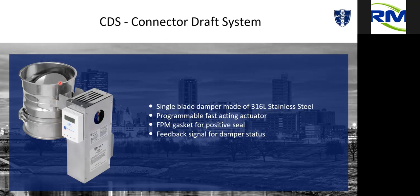Question came up, what sizes? These come from 4-inch all the way up to 16-inch. They're not designed to be used as a system damper. I've had several people ask me that, to where they just want to put one in for 3 boilers. The problem is that the control interlock just doesn't have that capability. So we would have to go to our multi-blade with a system controller. So this would be for individual draft control on each appliance.